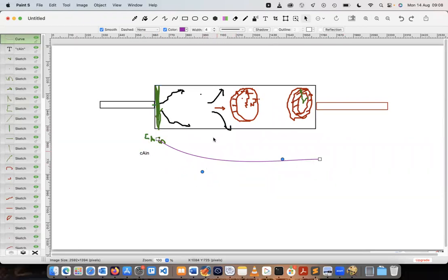Although something is happening out here, in terms of A being deposited onto the surface, it might be the case that we reach a stage where we've so depleted the fluid in the pipeline that the deposition of A is no longer significant. We don't have much further deposition happening. And so by the time we reach the exit, there's no gradient here. Of course, we are talking about variations axially. And so that means the axial gradient has died out.